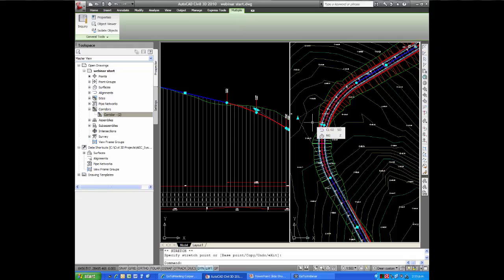This is a really good feature for one particular job that I had to do, building a road into a very, very tight, steep gully. I could just sketch out where I thought it would go, build the whole corridor and road and the whole model, and then just play around with it, adjusting it in and out of the hillside, changing the grade and where my vertical changes of grade occurred, and just move that road in and out of the model, in and out of the natural ground surface, until it had all the properties I wanted in terms of cut and fill and its actual alignment.